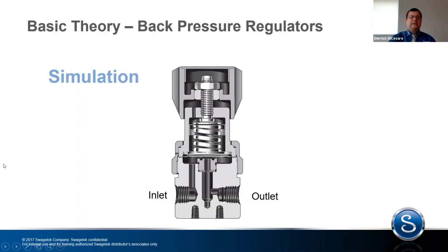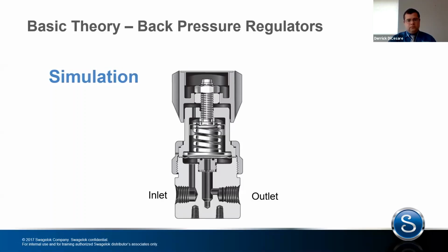So we're going to see this in practice. Here we go. So we're applying a pressure to the spring. So right now we're closed off. You're going to see our inlet pressure start to build. And as soon as it hits that cracking pressure, you're going to see the excess vent to the outlet until the system is exhausted enough that it comes back to the set point that we're trying to achieve. Again, very similar to a relief valve.